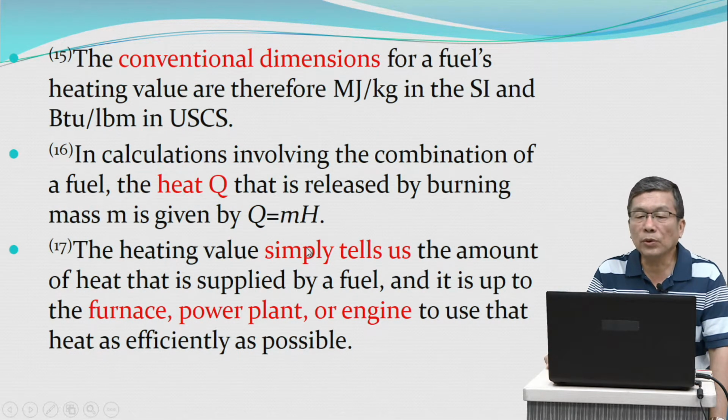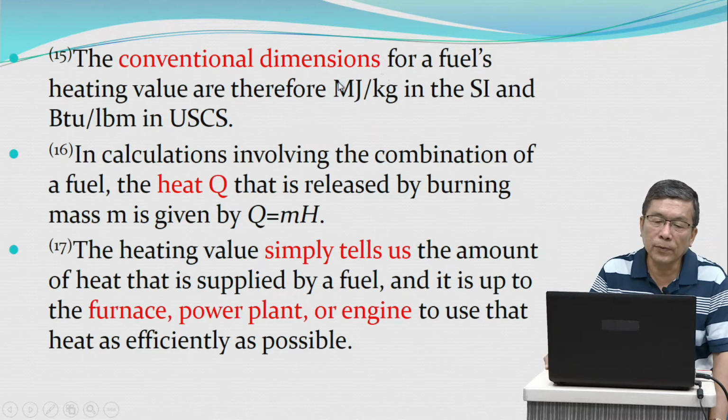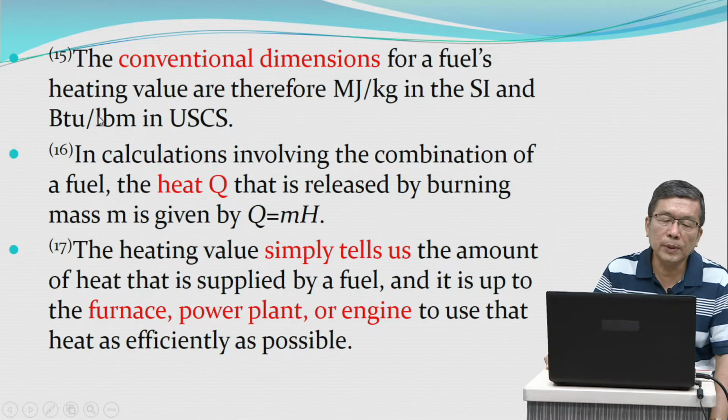The conventional dimensions for the fuel's heating value are therefore MJ per kilogram in the SI system and BTU per pound mass in the USCS.